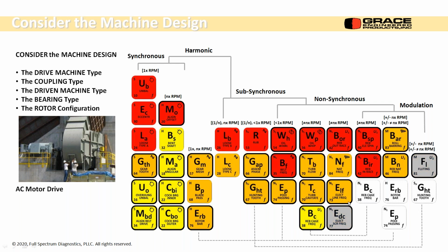So I have an AC induction motor. I can get rid of DC electric problems and fluting, as long as this, and you might not know what fluting is. It's electrical erosion of the raceways in the bearing from discharges of either current or voltage. So if this was a DC motor, that occurs sometimes. AC induction motors on variable frequency drives, it can also occur. But if it's just an AC induction motor, usually it's electrically pretty good, and you'll never get the erosion problems.